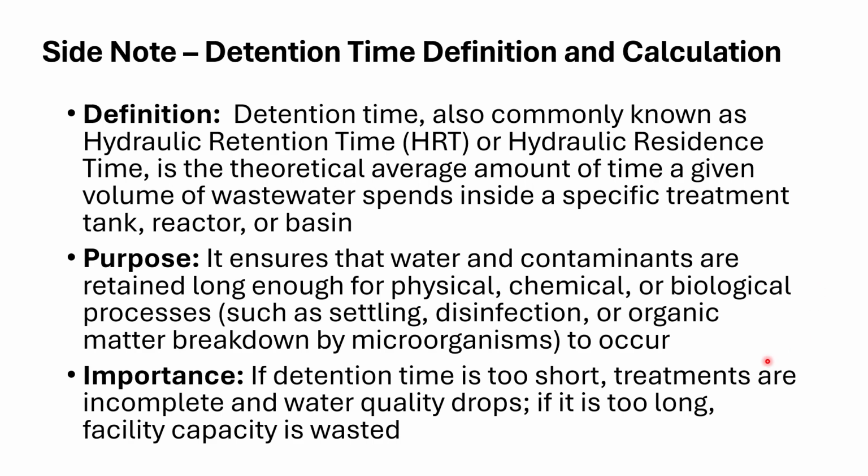And it's important because if that detention time, or the amount of time the wastewater spends in a certain process, is too short, well, then that process isn't going to be complete. And the wastewater effluent quality leaving that process isn't going to be what it needs to be for the other processes to be effective down the line. And if it's too long, the entire facility is just kind of standing still. So we're not operating in an efficient, cost-effective manner.